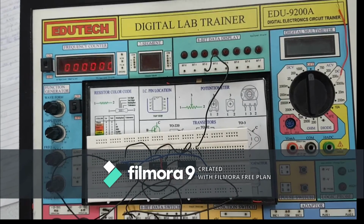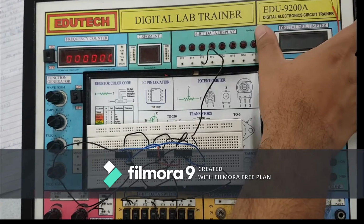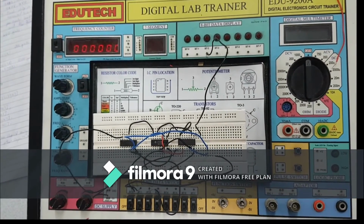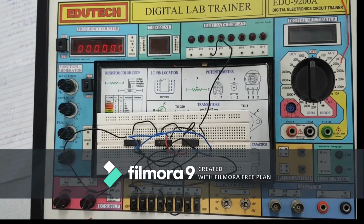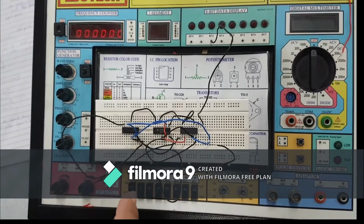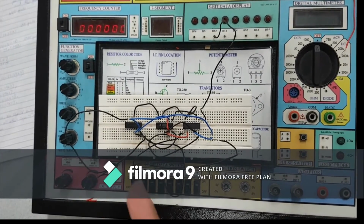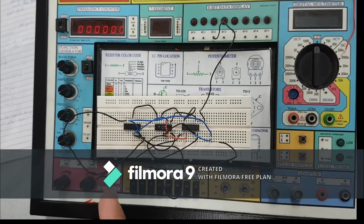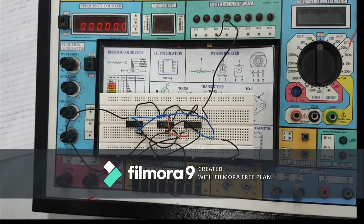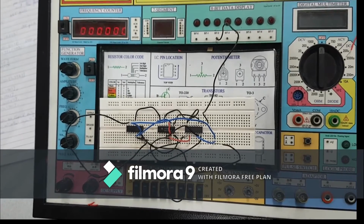This is our setup. We have used our breadboard and a digital lab trainer to make the work easier. In our circuit we have used 3 chips: the 7404 chip, which contains the NOT gates, the 7432 chip, which contains the OR gates, and the 7408 chip, which contains the AND gates.